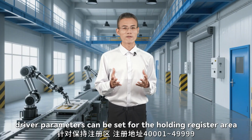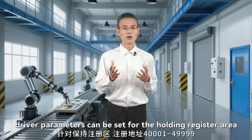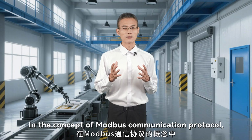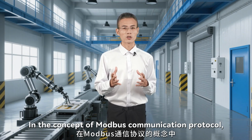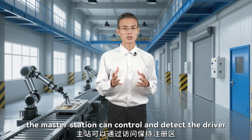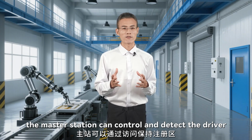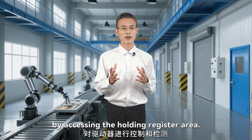In the servo drive TAD 8811, driver parameters can be set for the holding register area. In the concept of Modbus communication protocol, the master station can control and detect the driver by accessing the holding register area.